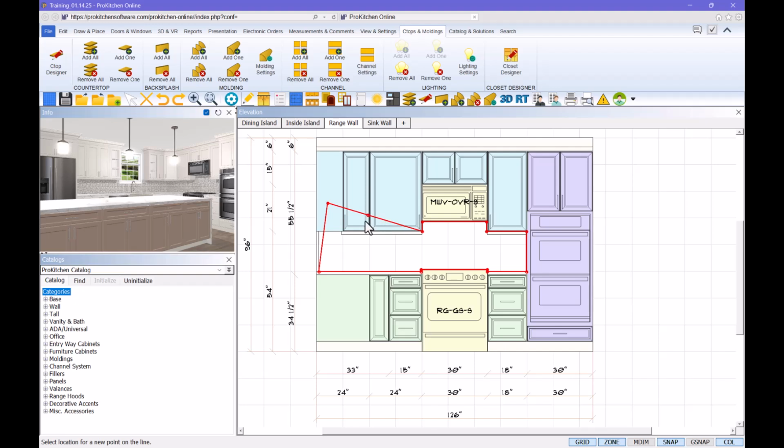Once you've moved the point to the desired location, left-click to secure. Now, this newly added point may be selected to change the shape of the object. Move it into the desired shape and left-click to secure. If you want to undo this shape, here is where you can use that Intersect tool. Right-click on the line, select Intersect, then double left-click the line that crosses the line you have selected the tool